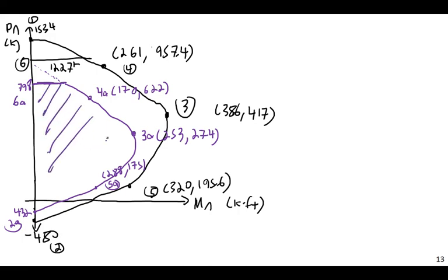Once we have this, again, this would be much better if plotted on graph paper. This is something you really want to do on graph paper, but this is how you ultimately design concrete columns. Now, often you do this assisted by software, definitely, but this is the basic process, and there are a lot of pre-calculated ACI column design curves that you can use.